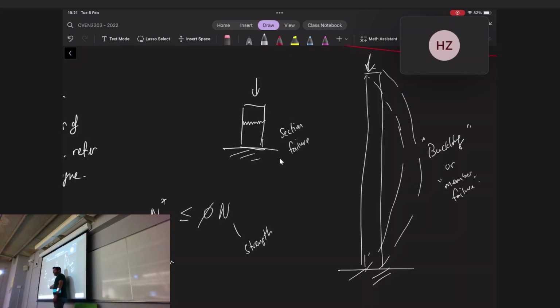Finding out what the design action is and what the strength is are two different tasks. Okay? So the design action has got nothing to do with the strength of the column. It has everything to do with what is sitting on that building. Right? Because whether you put a concrete column there or a steel column there or a timber column there, that thing is going to experience that amount of load. Right? Because of all the crap that's sitting on top of it. So design action is what it will eventually experience when you install it. This only has to do with how strong the material actually is, or how strong that column actually is.